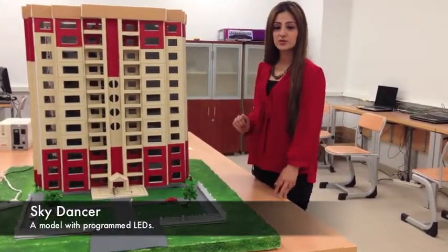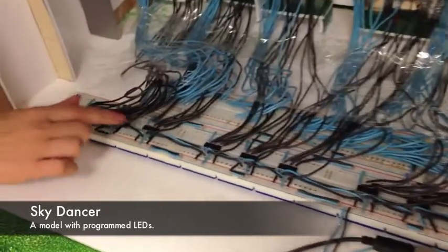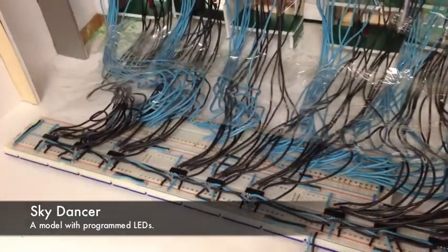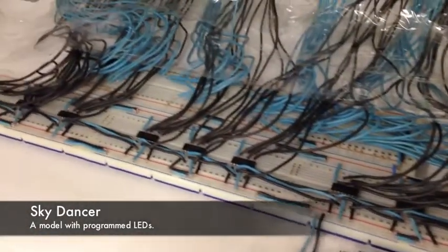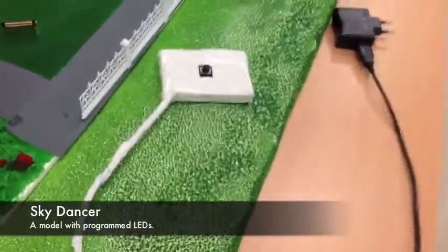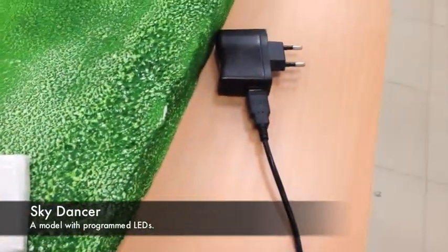I'm going to open the bag to show you what's inside the model. These are the LEDs that are soldered with wires, and I have connected all of them together on these breadboards. I have used shift registers to connect all the 72 LEDs because the Arduino microcontroller has limited pins, and each LED has a resistor to limit the current, and I have a push button which allows you to change the patterns of this model, and I have an external power which gives power to the LED.